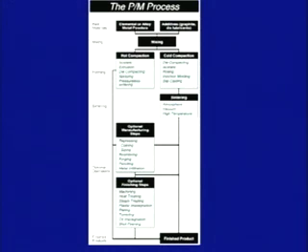Similarly, we call this process the process of compaction. This compaction can either be hot compaction or cold compaction. In hot compaction, there are a number of techniques which can be used, like isostatic compaction, extrusion, die compaction, spraying or pressureless sintering.